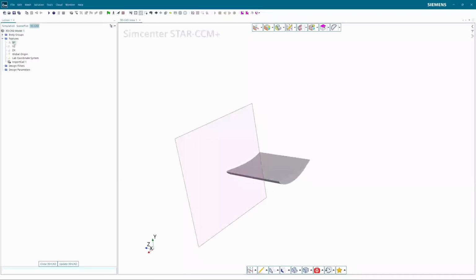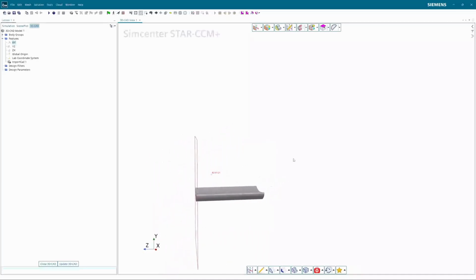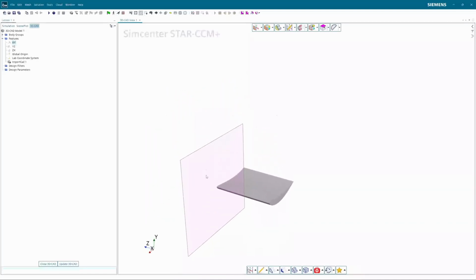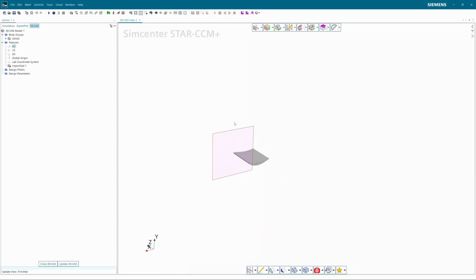So this XY plane here is the Z equals 0 plane, and your part needs to be right on it. I designed my parts in my software in the way that it automatically is there, but if you're importing points, make sure you draw those points on this Z equals 0 plane and then extrude from there.